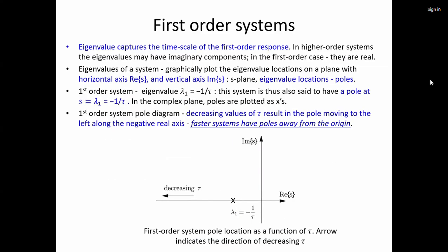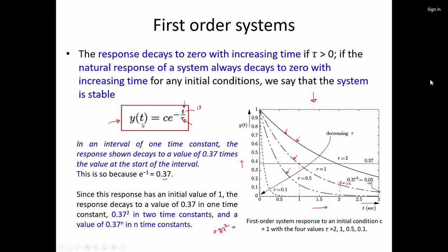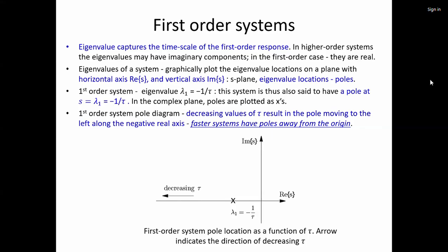Now, I think you should also learn how we can represent first order systems on a frequency diagram. Typically, we talk about this in the time domain, where the output is a function of time t. But these first order systems can also be represented in the frequency domain. From time domain to frequency domain, you can go by what is called the Laplace transformation.